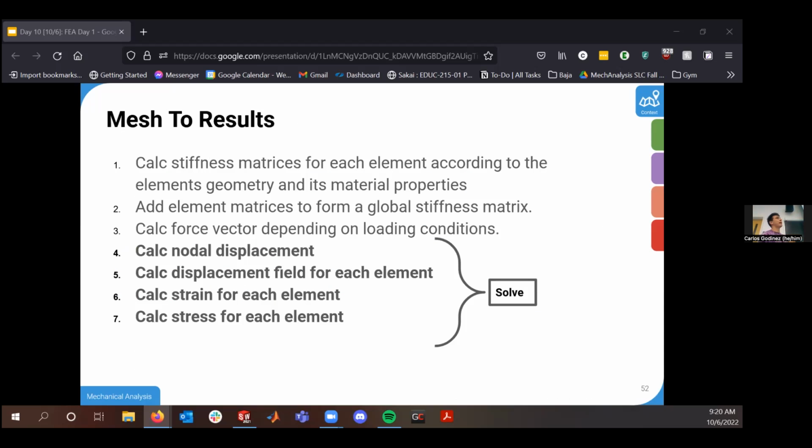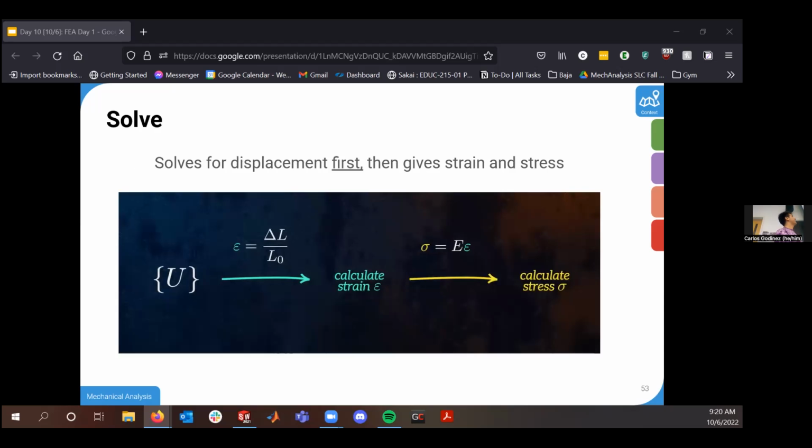And the last final discussion is how do you actually calculate those displacements. We'll talk more about that next week, but the basic understanding, and what I think is kind of cool, is that in engineering, what we've done in this class so far, we've gone from using my loading and geometry to solve for my stress. And then from my stress, I can look at my stress-strain curve and use Poisson's ratio and Young's modulus and go to my displacement and everything here.